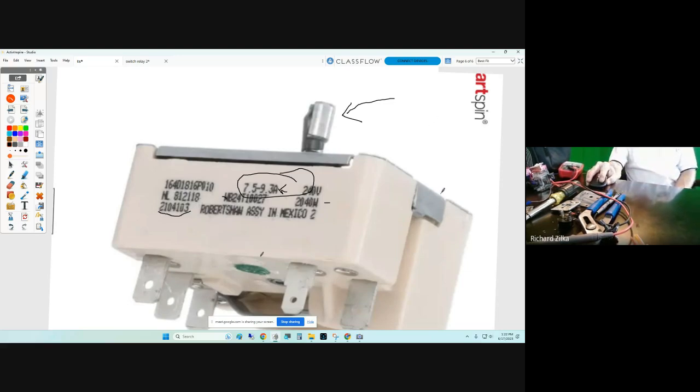And when I opened up the one that I opened up for you guys today, I just took a pair of pliers and bit it here with my channel locks, and just bent this piece out, and the top cover comes right off. So next time you change an infinite switch or you find an old stove, take this switch apart and look inside of it. What baffles people a lot more is the new dual burners and the dual burner switch and how that works. Well, get an old one or buy a new one.